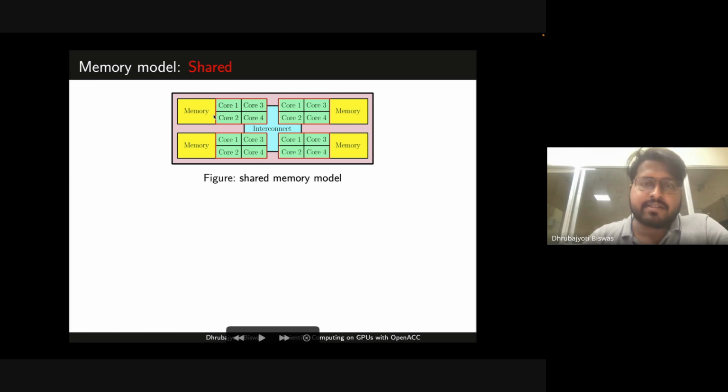But there is a slight difference. If you look at the diagram, you will see that the memory is shown as directly attached to these four cores. What I mean by this is, these four cores have fast and direct access to this memory. Since it is in hardware, it is put right adjacent to it, and the memory controller for this memory's RAM is directly embedded into the first CPU, which is this one. Same thing goes for this, this, and this, all three.